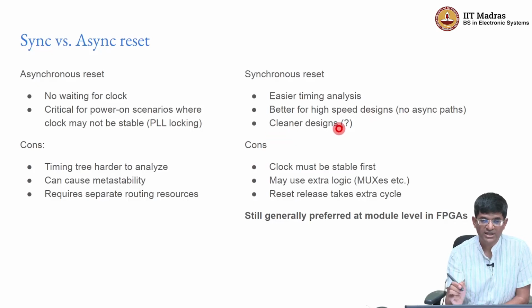Now this is more of a subjective issue, but there is an argument that can be made that this leads to sort of cleaner designs in some sense, right? Mostly related to the fact that you do not have these long reset wires all over the place that need to be routed in a different manner than the regular other wires that you have.